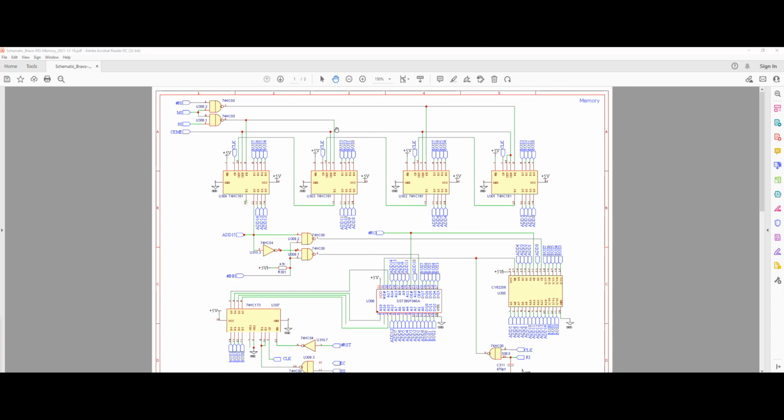And if you remember from our program counter circuit, we had some signals we called HI and inverted HI. As you can see, we are using exactly the same signals here to control that sequence. So let's say we want to read two 8-bit values in 2 clock cycles into our memory address register. What we're going to do is write the value onto our bus, and then bring the MI signal, which is the memory in signal, high.